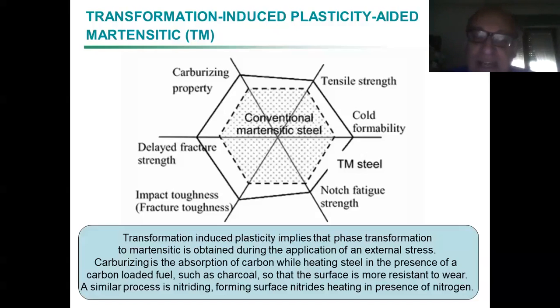So you have a kind of calculation of the expected life of an accelerated aging of a wheel with notch, because you remember notch means a defect. You create a defect to show whether, for example, you may remember the fatigue limit, that there is a fatigue limit for steel. The fatigue limit does remain or not for a definite number of cycles.